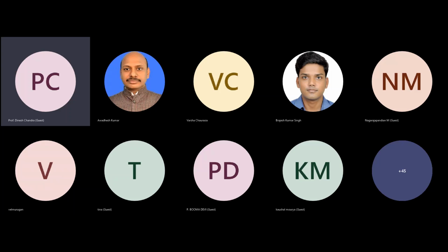So those who are working in the area of reduced order models must know that the choice of the order of the reduced order model can also be determined using TBR, because we write the matrix in such a way that the important singular values are in one place and lesser important ones are in another place, and we are able to truncate them.